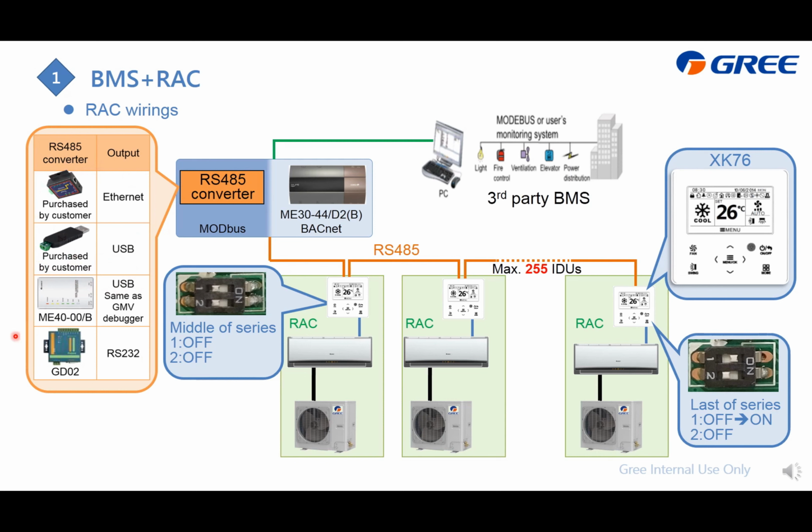On the other hand, as it is RS485, to ensure the communication, if this wire controller is located in the middle, there is no need to turn on the built-in resistor, which requires changing the built-in switch; not turned on means all at off position, just like this. And if this wire controller is located at the last, you need to turn it on to ensure the communication, and the setting is just like this. Just change the first switch from off to on.